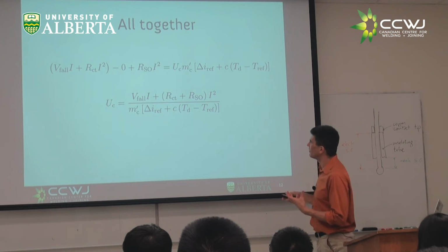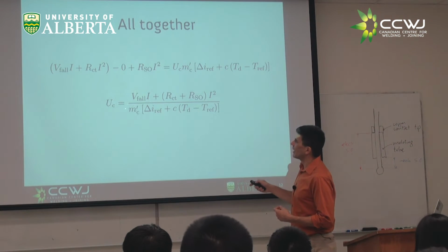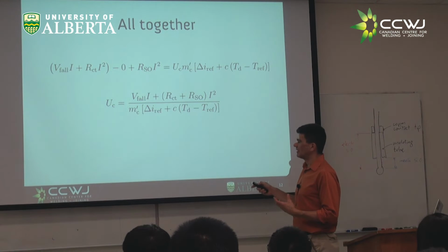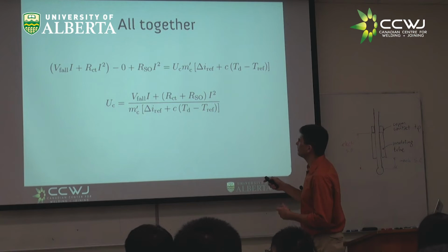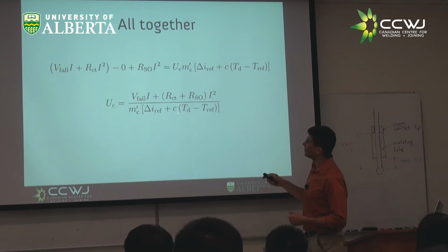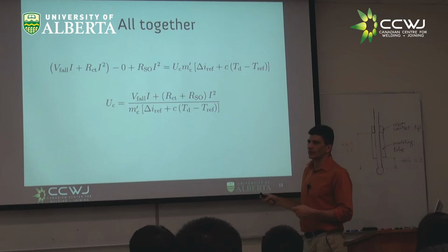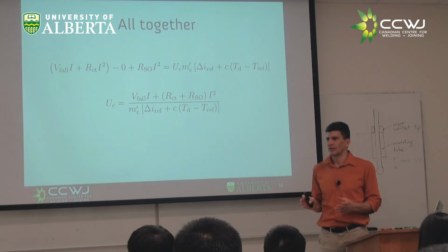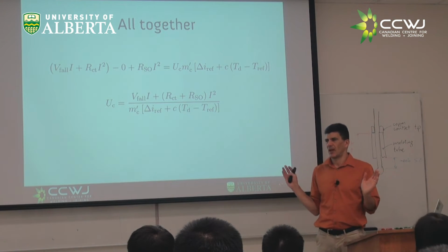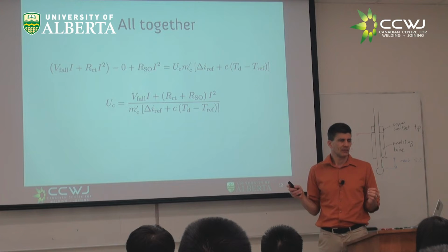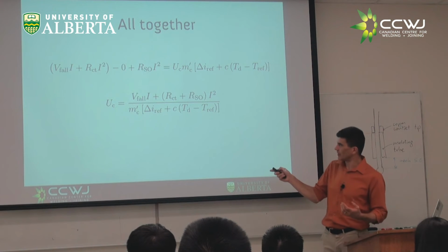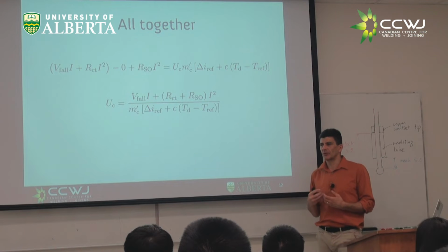Isn't this quite amazing? Down here I have the linear density, the linear mass of the wire, how many kilograms per meter. And here I have my enthalpy, that is a reference. And here I have specific heat and droplet temperature. If I have a hotter droplet, question to you, if I have a hotter droplet, for whatever reason, do you expect more wire feed speed or less wire feed speed? Less wire speed. Hotter droplet is less wire feed speed, right? It's dividing, right? And it makes sense because they take more energy.